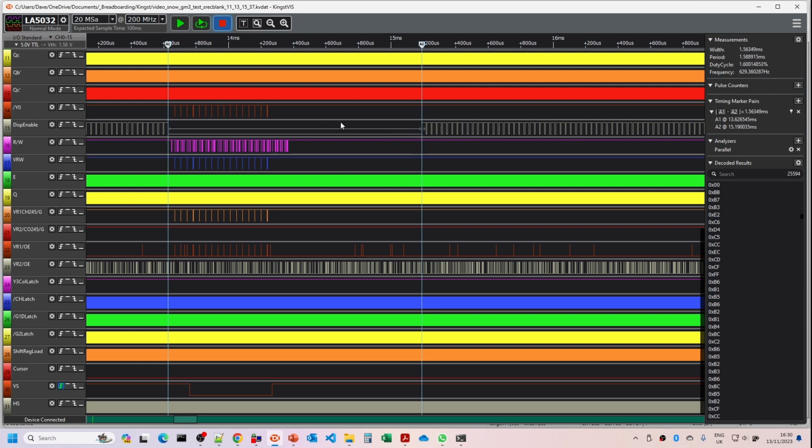So it would be possible to tune this and get slightly more updates going on in the video blanking period, but it really starts to become a bit more tricky to coordinate all of the reading from the serial port and things. What this indicates though is that by making sure we only do our updates, and this is the video read write plus also the Y0 chip enable signal for the video RAM, only during the video blanking period, then we avoid all of the mess on the screen.